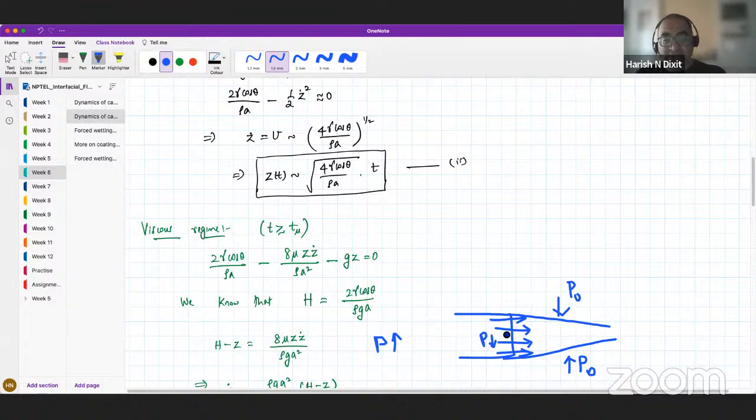If the pressure exceeds and goes further below the atmospheric pressure, meaning the pressure drops, you start off with very high pressure, but if it falls below the atmospheric pressure, and why would pressure drop below the atmospheric pressure? It could drop simply because it's moving at very high speeds, by Bernoulli's. If P exit is lower than P naught, the atmosphere actually pushes it in.